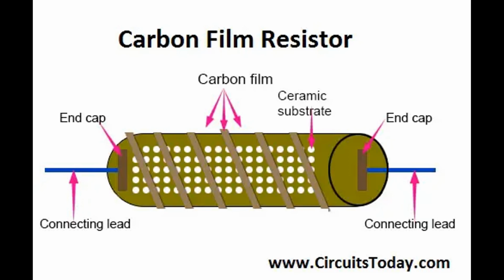End caps. The ends of the ceramic substrate are typically coated with metallic end caps. These end caps serve as connection points for attaching external leads or conductive terminations. They also protect the carbon film from physical damage and contamination.